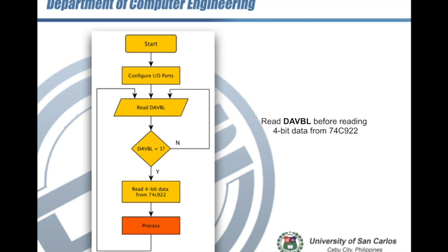It's because 0000 is the address of key number 1. So we should have a distinction between the keypad data 0000 and a keypad where none of the keys are pressed. So